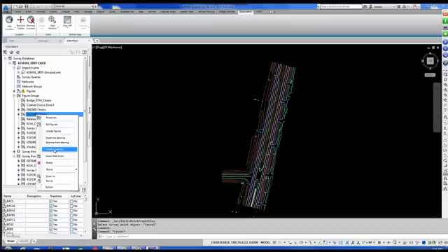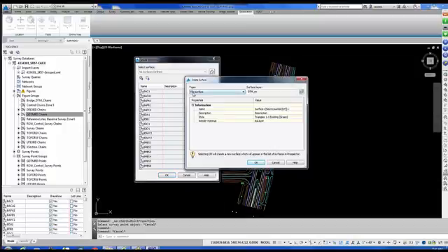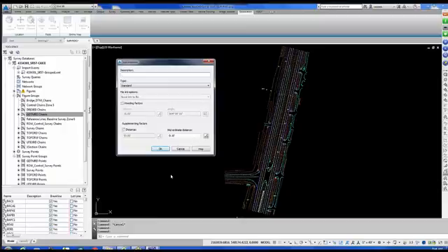There's an option here called Create as Break Lines. So I'm going to pick on Create as Break Lines. And you get a dialog box up that says Create Break Lines. Select the surface. I don't have a surface selected, so I'm going to pick on this icon right here to create a new surface. It's going to be a TIN surface. My surface, I'm going to call State Road 57 existing. How am I going to display my surface? The style I'm going to use is triangles 1 to 1. Hit OK. So now I have a surface to apply all these break lines to. I hit OK. It now says, when you're adding the break lines, do you want to give it a name? I could call it anything, State Road 57.